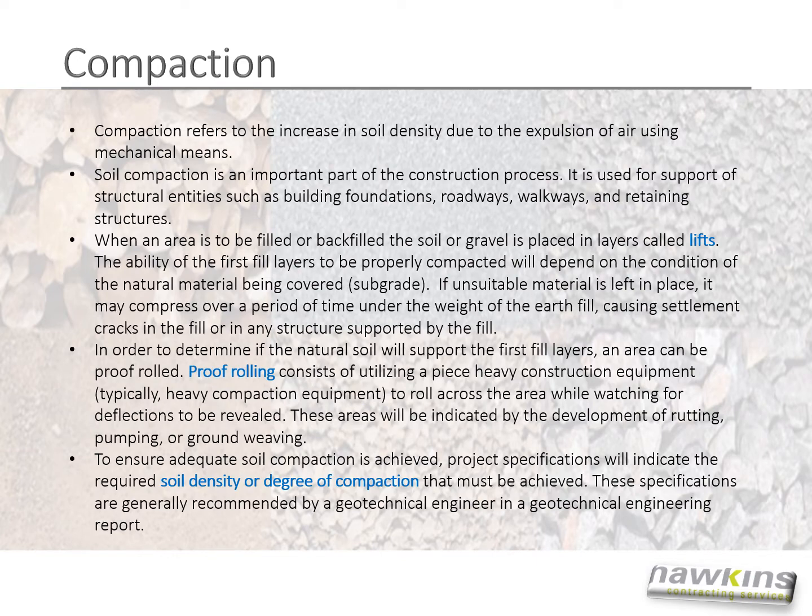Compaction. Compaction refers to the increase in soil density due to the expulsion of air using mechanical means. Soil compaction is an important part of the construction process. It is used for support of structural entities such as building foundations, roadways, walkways, and retaining structures.